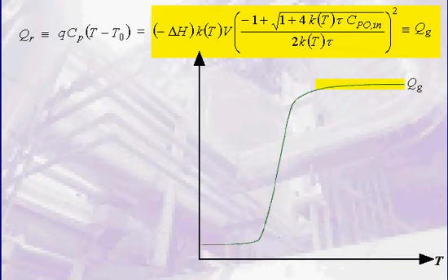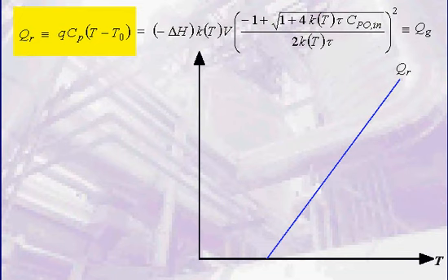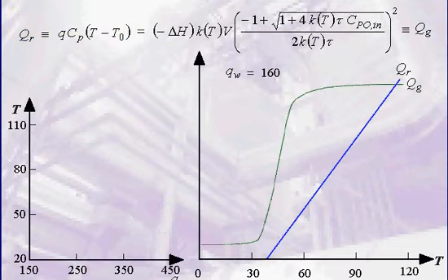In contrast, at high temperatures, a high rate of heat generation is expected, with a value limited asymptotically by the supply of reagent. The heat removal rate is linearly dependent on the reaction temperature and the total material throughput, Q. The energy balance is represented graphically as the intersection.